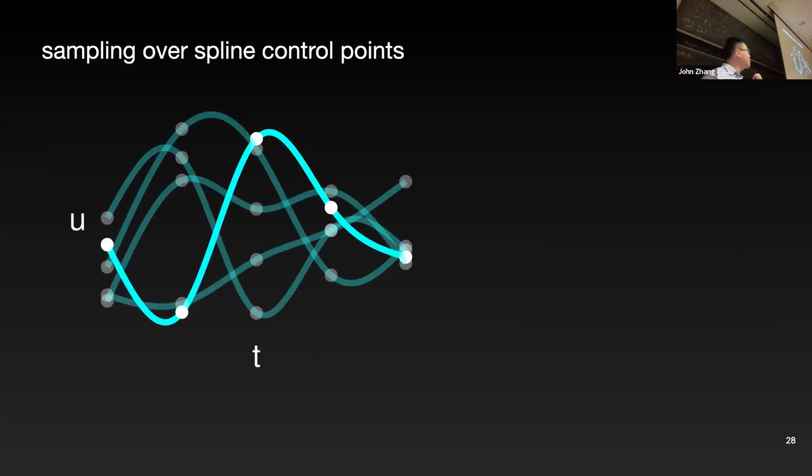So, the one trick to make this all work. We discussed this earlier: MPPI naively does not work well at all for high dimensional systems. The quadruped we're controlling has 12 actuators, and MPPI shouldn't scale at all; you typically want lots and lots of samples. I would argue that the one key trick to make this work is compressing the number of degrees of freedom in the prediction horizon into just a couple of control splines.